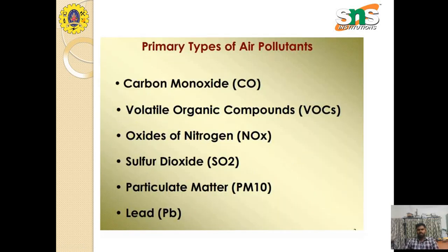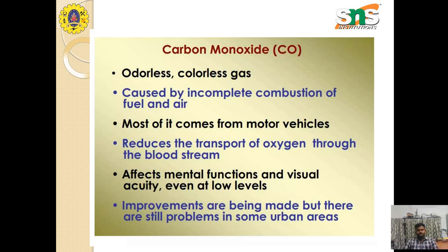The pollutants emitted from IC engines are carbon monoxide, volatile organic compounds, oxides of nitrogen, sulfur dioxide, particulate matter, and lead. First, carbon monoxide. This emission develops when an insufficient oxygen supply during the combustion process leads to the liberation of carbon monoxide from the internal combustion engine.